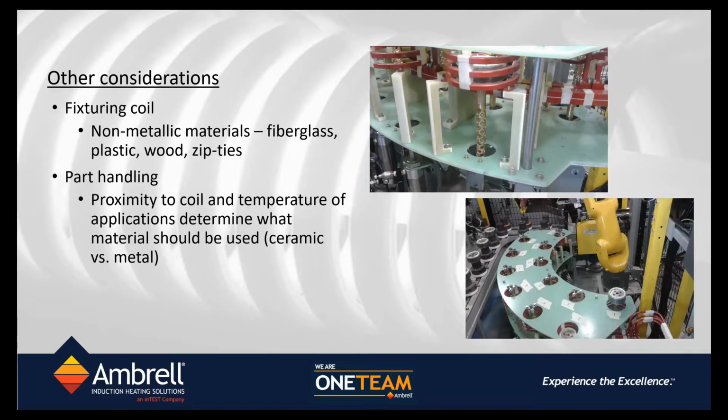The fixture is basically a rod, but it has holes drilled in it so that the heat does not just run down the rod or tube. This basically stops the flow of heat down the rod and preserves the heat that we are putting into the system.